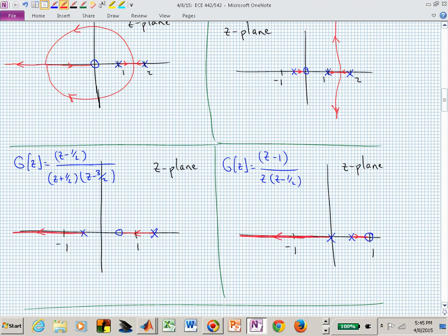And if they move consistently, which they may not, your hope is that that pole at 3/2 moves quicker in distance than that pole at -1/2. But if the gain, as you're cranking up that knob, gets to 1 on the right, and you've already zipped past -1 on the left, you can't stabilize that system with pure gain.